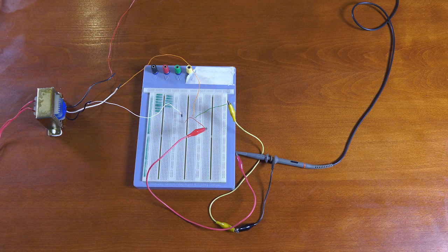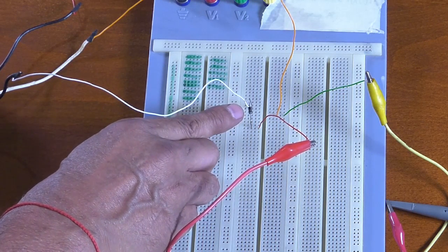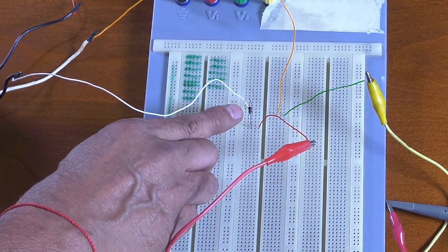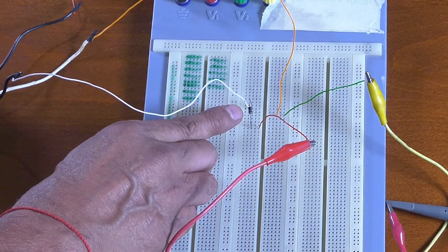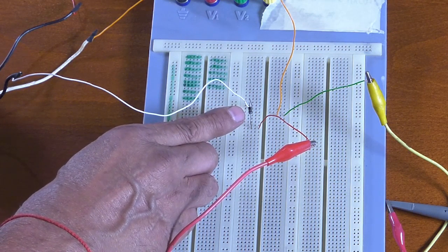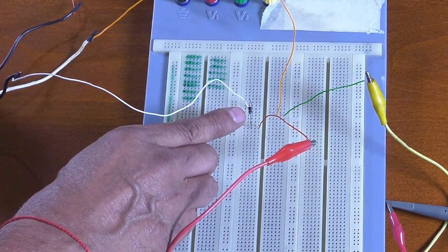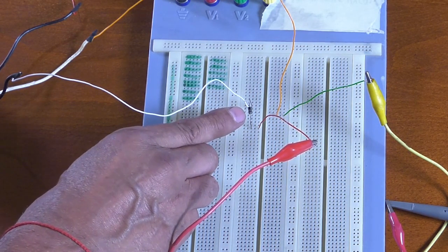One is called half-wave rectifier, where we use just 1 diode, as you can see there. And remember what a diode is. A diode is a component that only allows current to flow in one direction only. That is what we're looking for at the end of the day when we're talking DC. DC stands for direct current. AC stands for alternating current. Current that changes every so often.